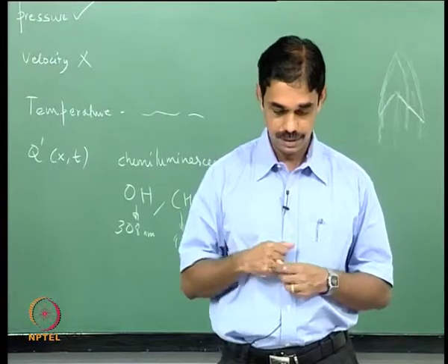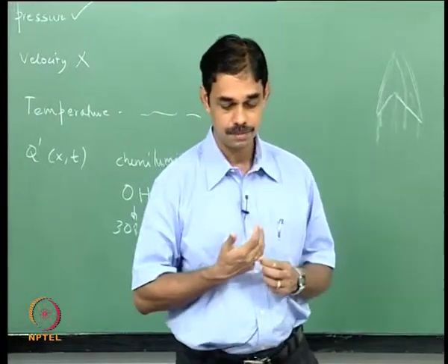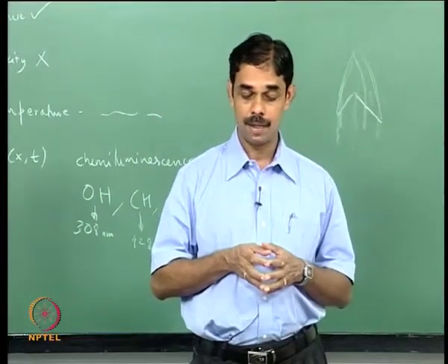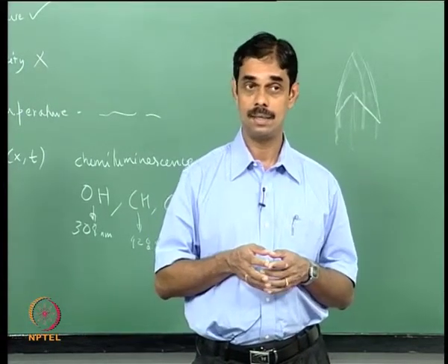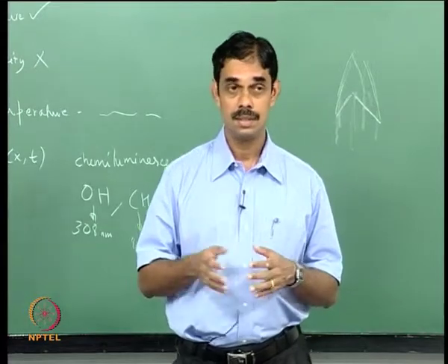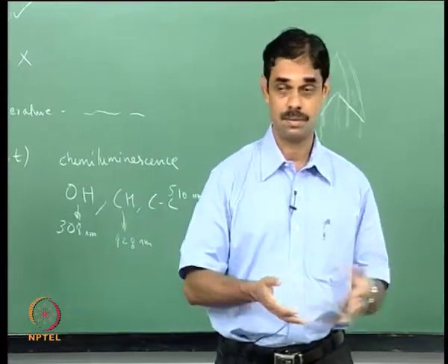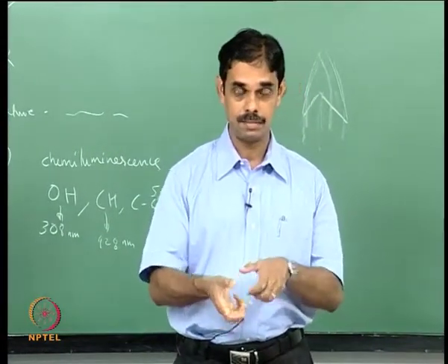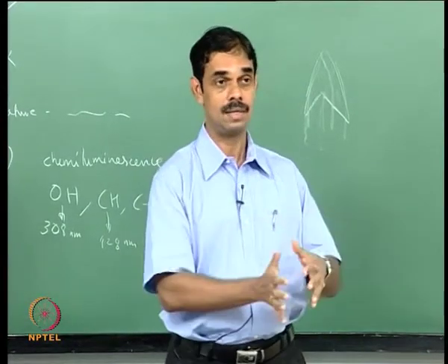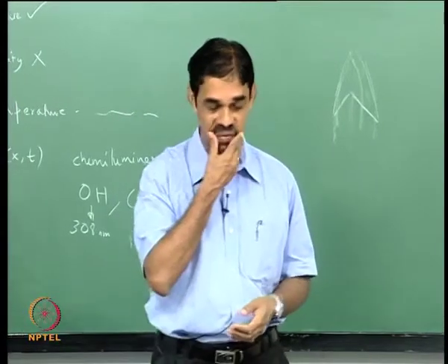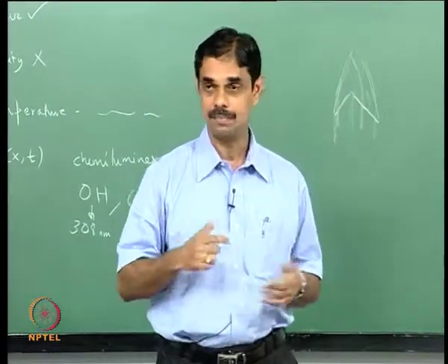So we need optical fibers. There is a limited field of view, and the readings will be quite noisy, and another problem is the flame may shift its location, so you may keep the thing focused somewhere, and the flame may be one way during one mode, and go somewhere else during another mode, and so you can have a lot of problems. So it is difficult, but you can do it.